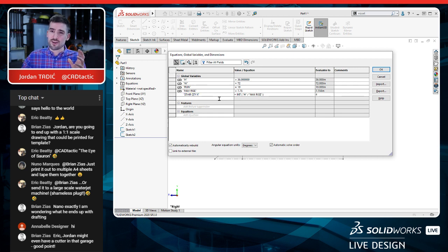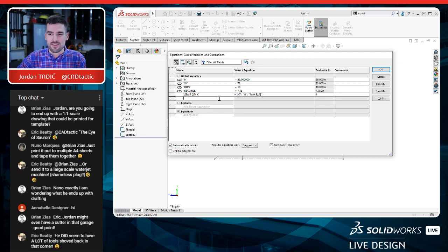In some cases, depending on the overall height, we might divvy it up just perfectly where the maximum rise happens to be the exact stair height that we need for even spacing of stairs the entire way. But I can instead go stair quantity here, the actual stair quantity, and this is where we're going to get a little smart. And again, if you're familiar with Excel, this will make sense. I'm going to do an if statement. If